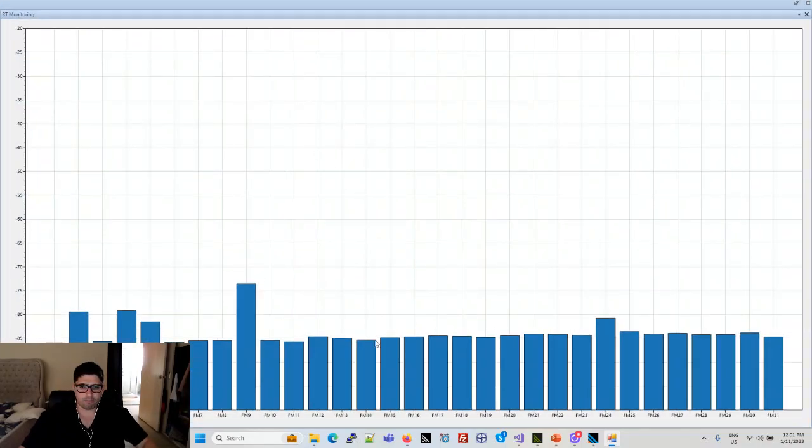So here I am monitoring a set of frequencies. You can configure this in an Excel spreadsheet. So I want to monitor specific channels, and then the tool automatically will start capturing measurements and graphing these measurements. They don't have to be sequential. So it could be any frequencies in the FM band, in the AM band, in the VHF, UHF band.